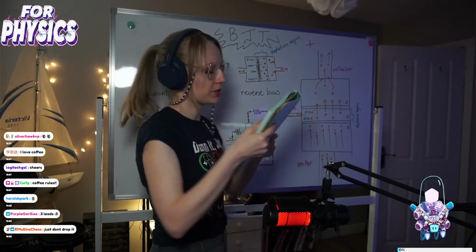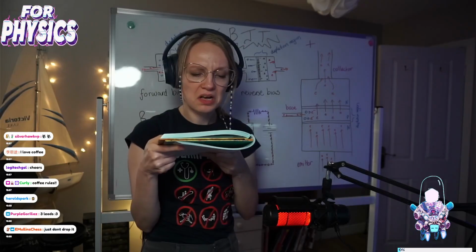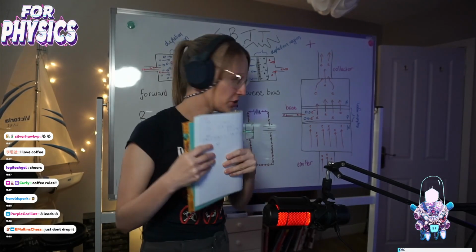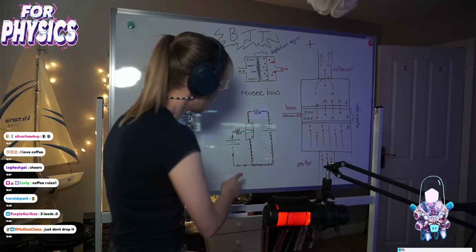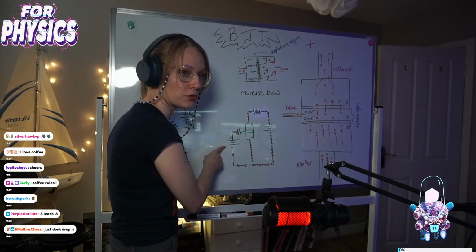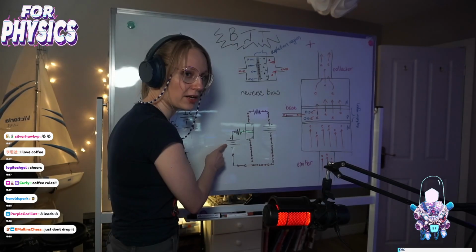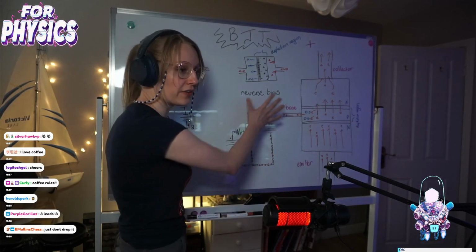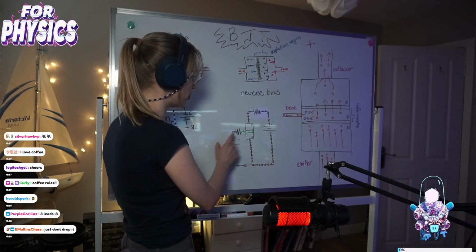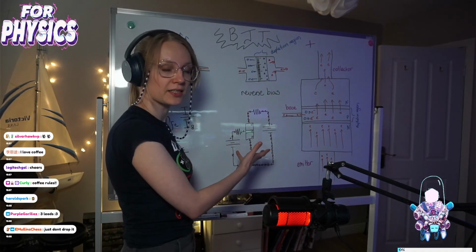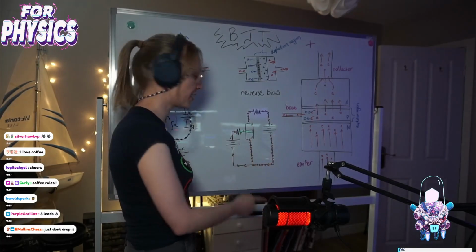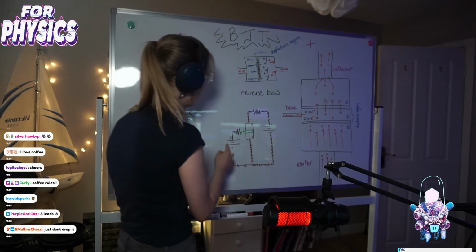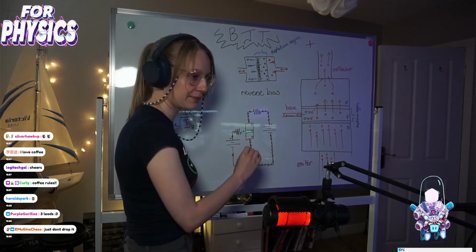Remember that. Now, what did I write here? Yes. So, we've set up this circuit where we put a voltage source in our circuit. Let's say we have something like 0.2 volts operating. Nothing happens. If this is operating at 0.2 volts, there's not enough voltage to get the electrons across the diode. Nothing happens. However, let's say, magically, I'll say this number, 0.7 volts. We set this to 0.7 volts or higher.